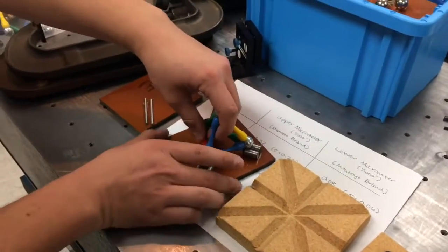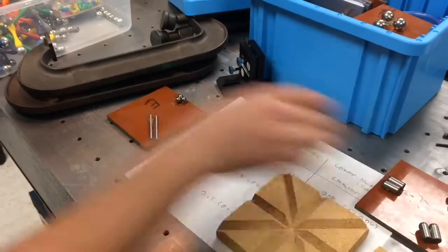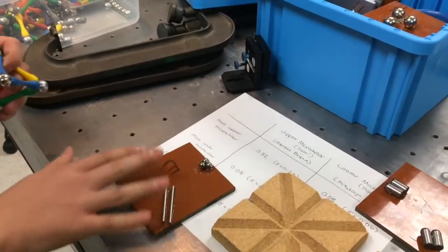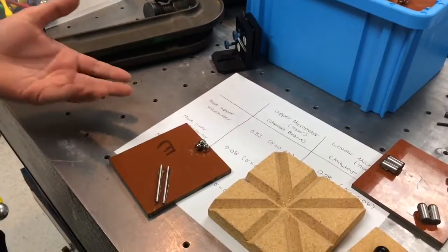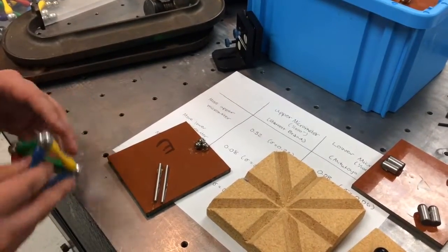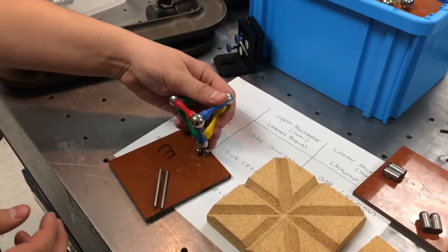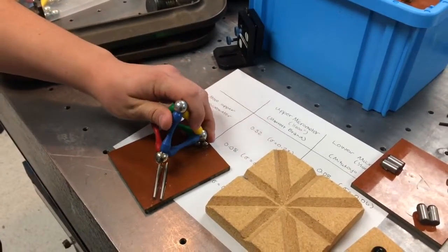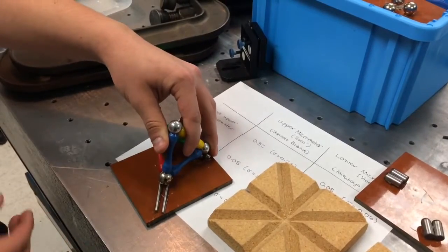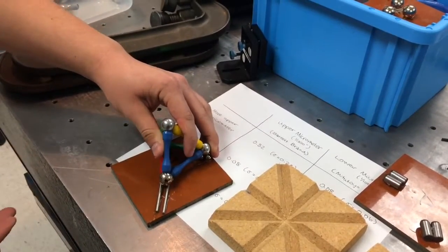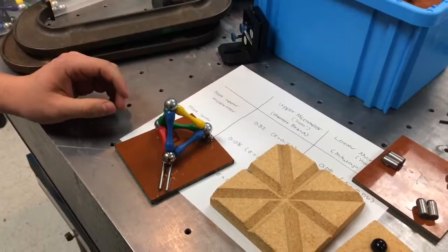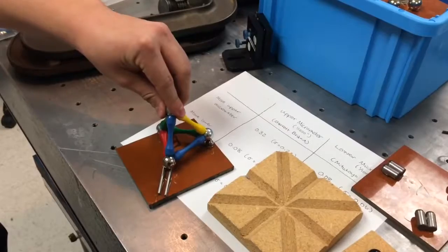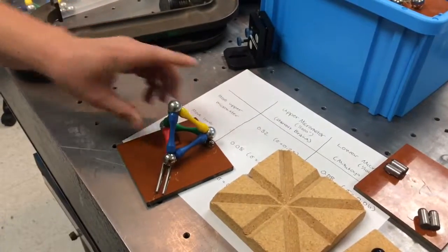Correct. There's another main type of constraint that you see a lot, and that is the cone, groove, and flat. In this case, the cone is not a cone, but rather a set of 3 balls, but the principle is still the same in that it provides 3 points of contact for the first ball. The groove provides 2 more, so that's 5 so far, and then finally the last ball rests on a flat, which is 1 point of contact and is the 6th point of contact, perfectly constraining the system, and you can see that this optical mount no longer moves. So those are some of the main types of kinematic constraints.